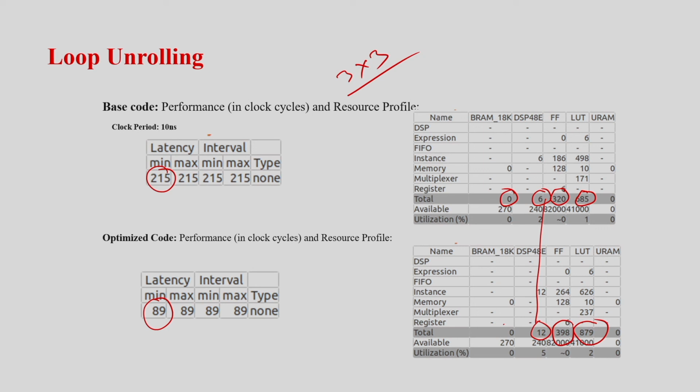Okay. So, I can clearly see that if I just apply unroll there, my latency improves 3 times, the number of clock cycles needed is reduced by 3 times, and my area overhead is not 3 times. So, this is useful, right, because performance is greatly improved. Now, one might ask me that if I do not unroll, why is it taking 6 multipliers?